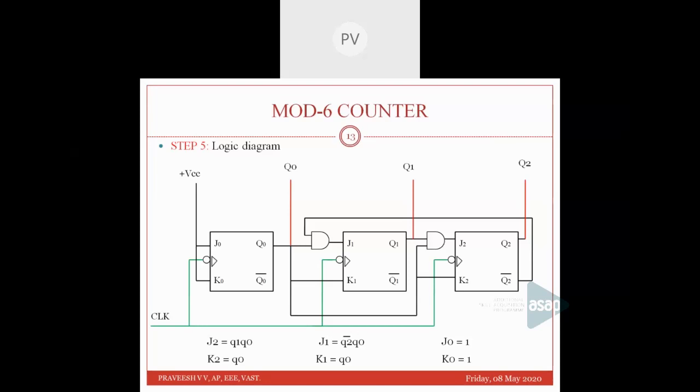So there, instead of the capital N, you have to use 8. So that condition has to be checked. So to count 8, you know that to represent 8 in binary, we have to represent it by 1, 0, 0, 0. So basically you require 4 flip-flops.